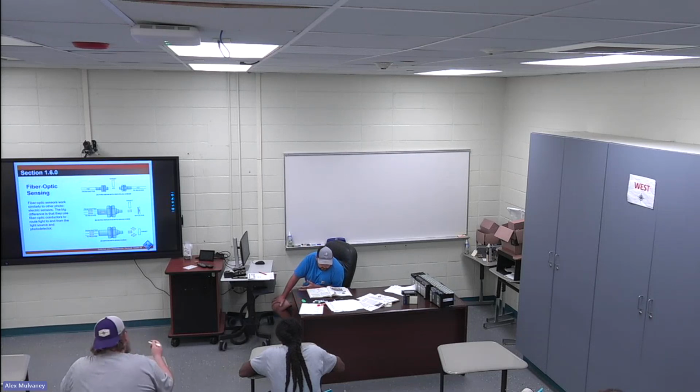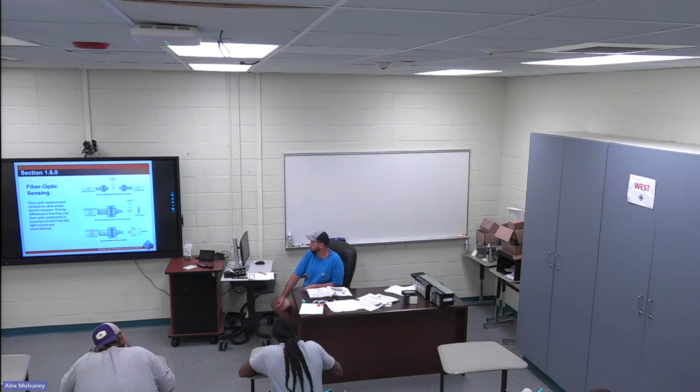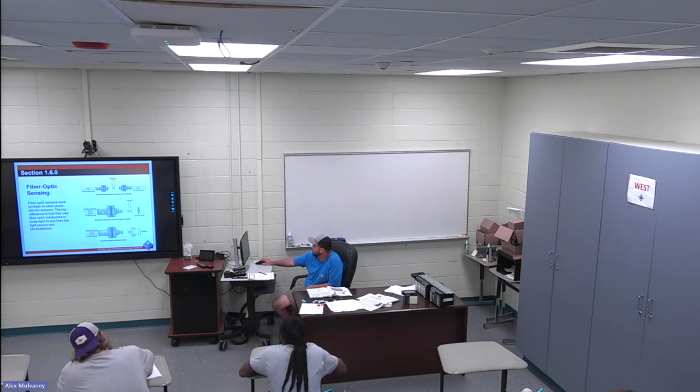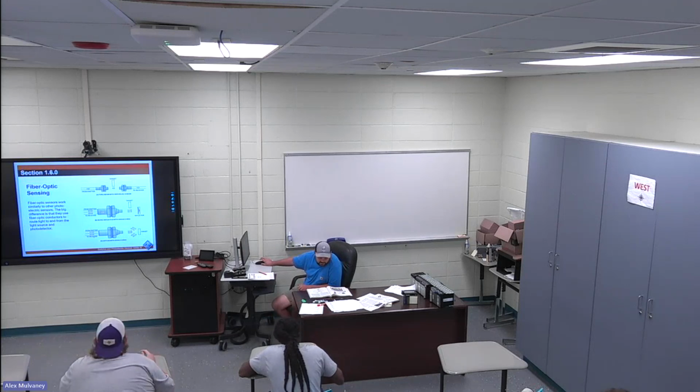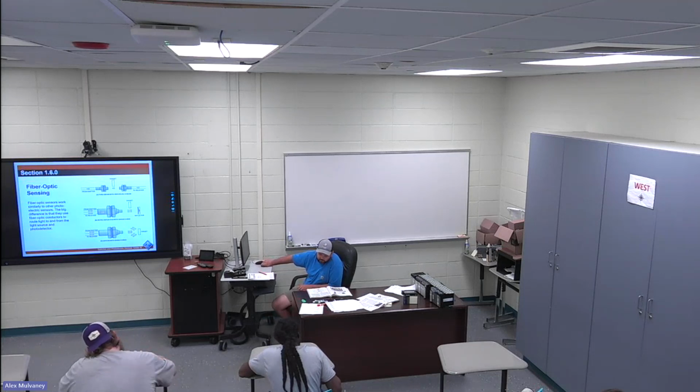Online test question. Next paragraph, second and third sentence. Figure 28A shows the through beam method in which the light is emitted and received with individual cables. The target either breaks this light transmission or allows it to pass from emitter to receiver. So these 3, you need to memorize and learn. They're going to have all 3 of these on the test.